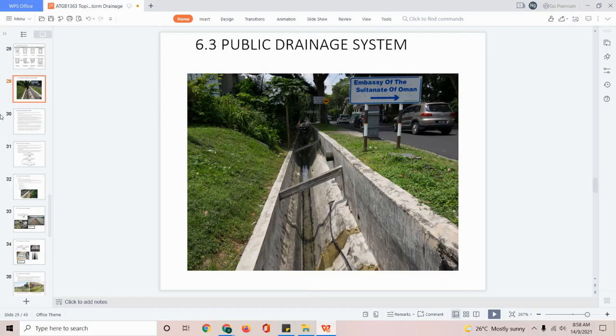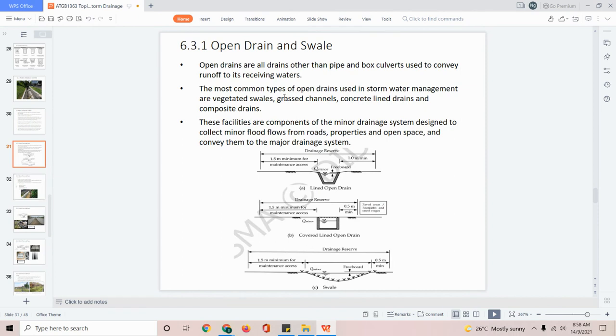So there's actually two levels. So it can be open or it can be swale. So when it comes to open, it's all man-made, meaning we have concrete precast drainage. We call it a pipe or even a box culvert, depending on the size and the material. So these are there to facilitate the major drainage. And then swale is a man-made natural feature, or drainage. So this is what we call a swale.